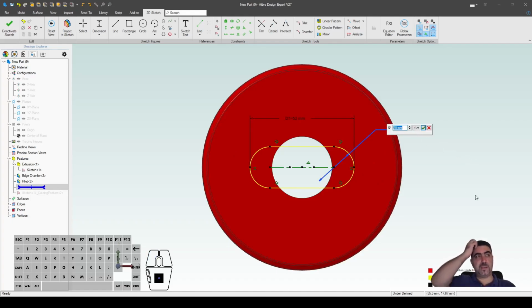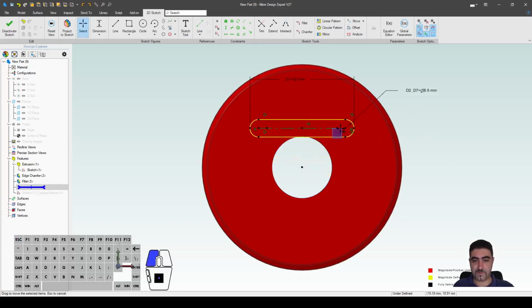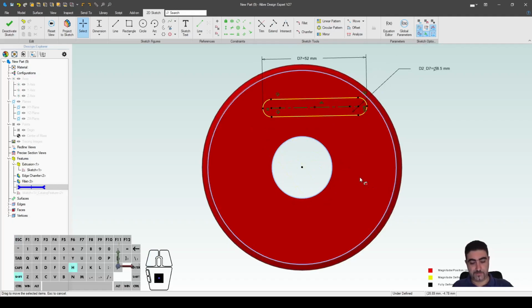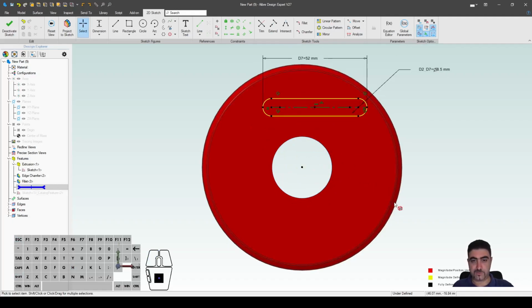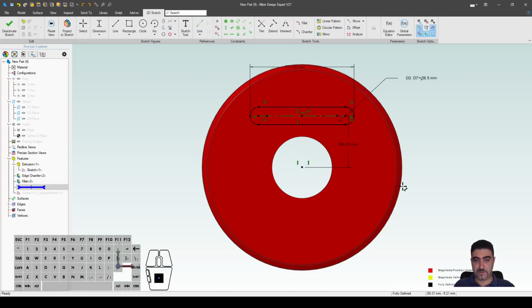And I will be using M8 screws. So the clearance for an M8, the loose clearance, let's do the tight clearance. I think it's 8.5. I think the loose clearance is 9, but anyway, okay. So I also want this horizontal. I also want the midpoint to be right above the center, and I want this distance to be 25.